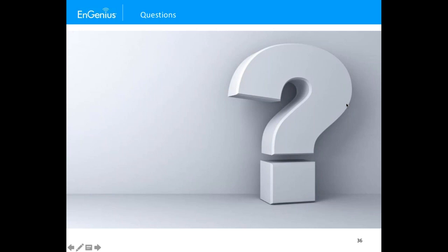As you're going up and down in that axis, that would be marking your vertical beam width, and that is only 3 dB down, which means your other steps down are multiples of 3. So the next steps down off your primary beam width would be 6, 9, and 12, and so forth. That's the reason why in the point-to-point type of deployment, when I had something that was 90 degrees off from the primary beam width, I was still able to make a connection, because yes, it's 90 degrees off, but maybe it's only 6 dB down. Let's say its signal strength in the primary beam width would be negative 50, but because it's off, it's negative 56. That's still a strong signal. You still will make a really solid connection to that, and that's the reason why that will work. But if it's far enough away, that may not work, because of the distance and you're off the primary beam. But thank you for that question.